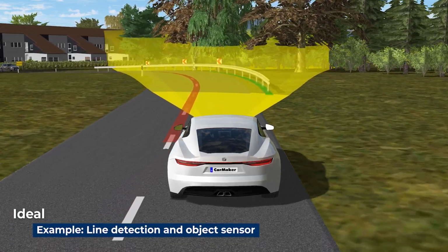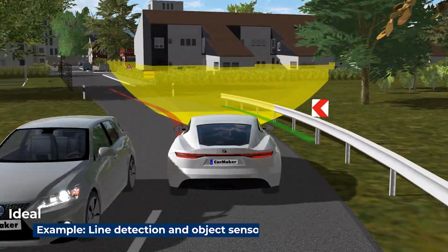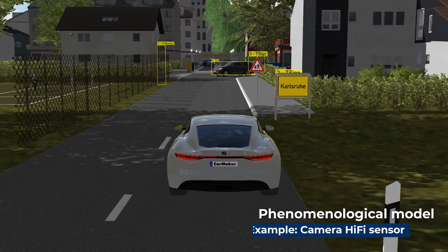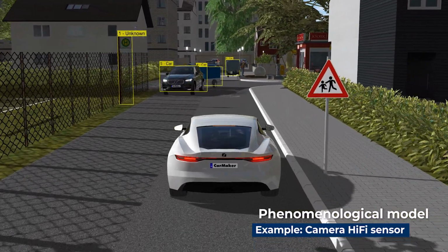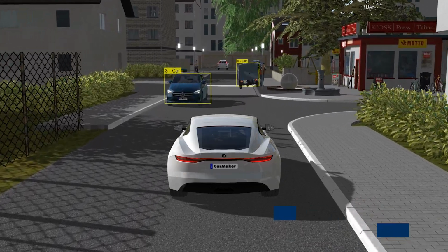If I am an OEM and buy one or more sensors for an ADAS function, I typically have no know-how about the perception software. It's usually built into the sensor or function ECUs themselves and delivered by the Tier 1. So I need a rather abstract model delivering an object list, either ideal or with some modeled phenomena, resulting in false positives and false negatives and noise on the object list.